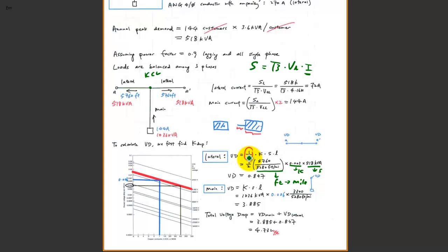We mentioned that for the voltage drop under this uniformly distributed rectangular model, you have to include the half constant. So basically, nothing is new here, except that you have to use the half value to multiply by the whole thing from the constant value. That gives you 0.847 voltage drop. Now that's just a drop from this point to both of them, right? This is a drop for the lateral. We still have the part from the feeder head to that point before the branch out to two laterals. This part we have to calculate.